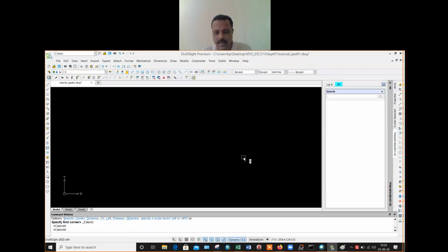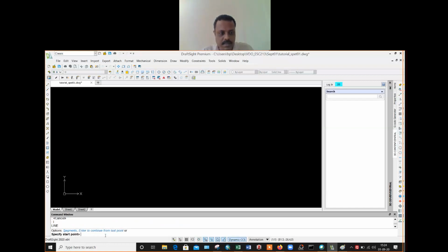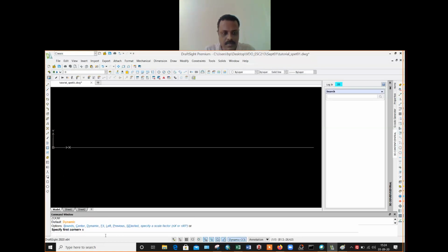Line, my start point is 0, 0, then @110<0. You see, now this is my 0, 0 and this is my 110 mm, from here up to here.